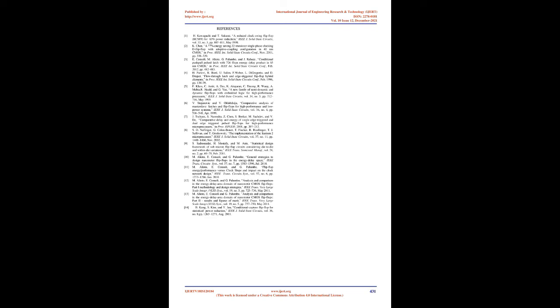As can be seen, the fastest DPSCRFF at 54 ps is significantly faster than the next fastest flops, HLFF and SOSPL, at roughly 150 ps. The lowest power DPSCRFF at 141 fJ is comparable to the lowest power flop, PPCFF, at 130 fJ. However, it has a propagation delay of only 167 ps compared to 342 ps.